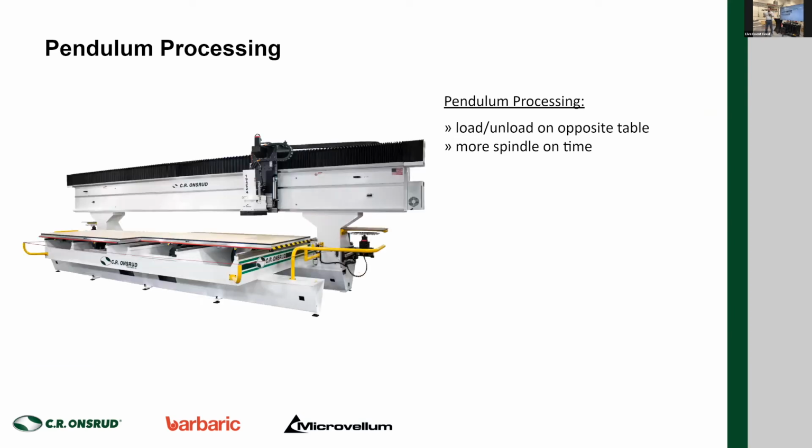Another feature we talk about again, and this is that value-added time, keeping that spindle running, cutting, making money. We have an option on our twin table machines, twin moving table machines that we call pendulum processing. So here you see on this machine 2 tables, and while the machine is cutting on this table, your operator is loading, unloading on this table. And when this one's finished, they switch in and out so that spindle will come over here, start cutting on this table, while the operator is loading and unloading the other table. Pendulum processing, keeping that spindle running, making the value-added time.